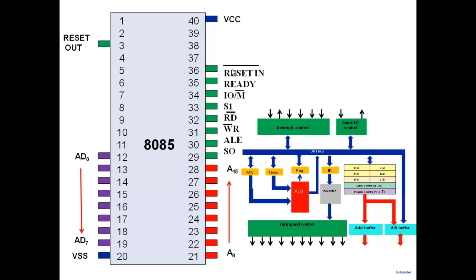These are all the external signals that I was talking about here, timing and control that you see here. So the microprocessor, for example, when a microprocessor wants to read from the memory, it has to indicate to the memory that I'm reading it. So it will give a signal on the read here. And read bar means it's active when it is low. So the microprocessor will indicate a 0 on this particular one, and the memory then gets a signal to place the data onto the bus here. So like that, there's a read bar, there's a write bar, and we'll see all of that, okay?